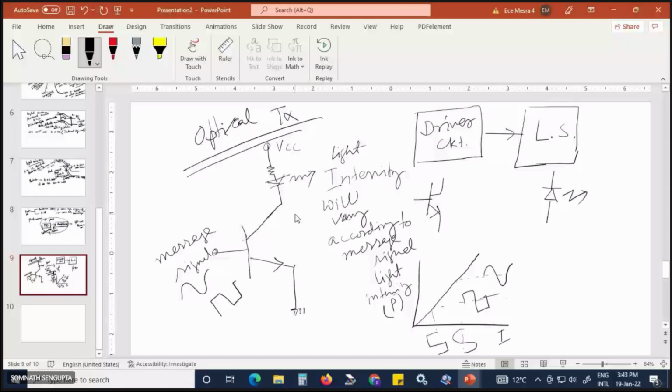To reduce the capacitance, generally an intrinsic layer is provided in a PIN photodiode. A PN junction is sufficient, but the intrinsic layer has the advantage that it reduces the capacitance by widening the depletion region. If you use an intrinsic layer, the depletion layer will increase.